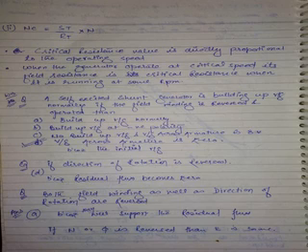Now if it is reversed, what happens? The current flowing into the field winding flows from FF to F in the reverse manner. If you want to make the flux negative, first one polarity, then opposite polarity, then while doing so it will make the flux become zero. At one particular instant, it will erase the residual flux also. Once the flux becomes zero in the machine, just think there is no stator: no flux means no poles, only the rotor rotating. What is the EMF induced there? Zero. Not even 6, not even 8. It is simply zero. So it doesn't build up voltage. Or, if the options give you 0, pick 0 voltage.